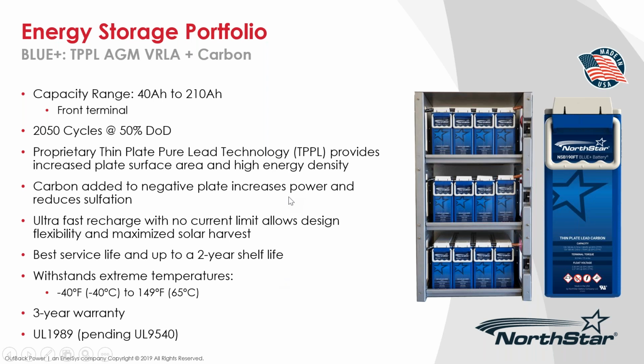Other thing I wanted to mention about these two batteries, the PLR and the Blue Plus, there is effectively no charge limit to them. I know we do have a rating on there, but as you push more energy through them, they will self-curtail that charging current. And almost all lead acid batteries do not have that capability. Where this is important is in applications where you're big on solar and small on batteries, because batteries are the most expensive part of the system.